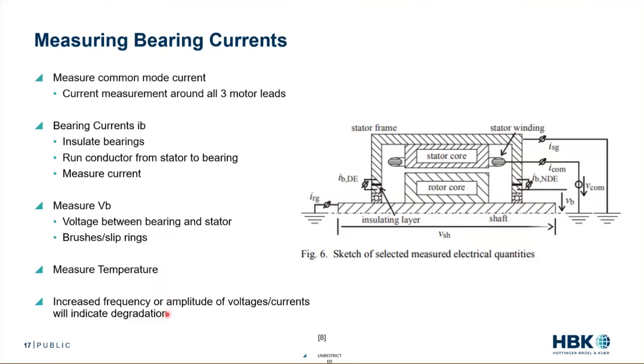And we can look at increases in frequency of discharge or increases in amplitude of discharge in parallel with increased temperatures. And again, identify that degradation over time and really see how that bearing behaves, how my total efficiency behaves. We can understand this whole system. Again, I think this is pretty exciting stuff, given that 40% or so of motor failures are coming from bearings. With a little bit of engineering, we can do a pretty good job at understanding what's happening.